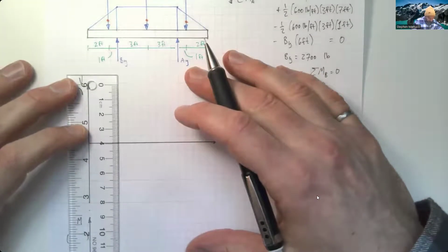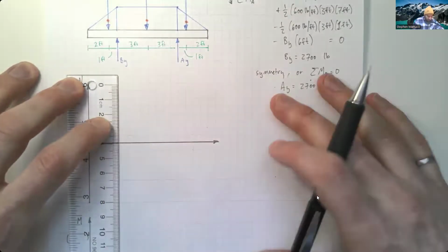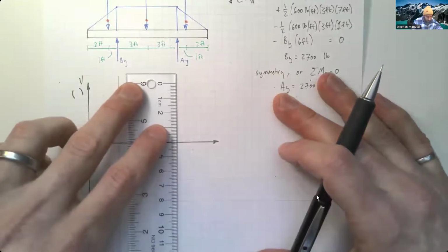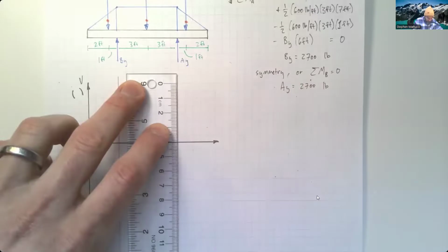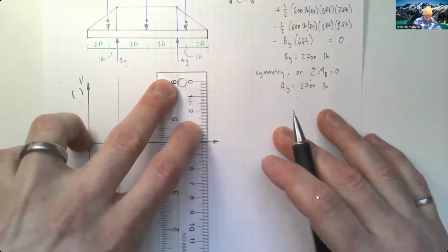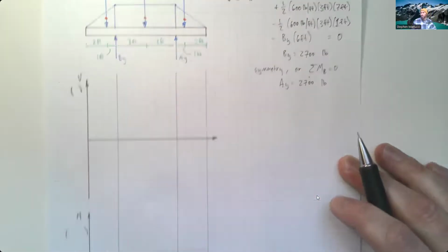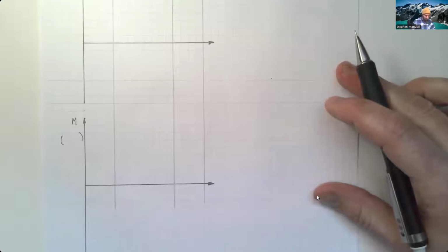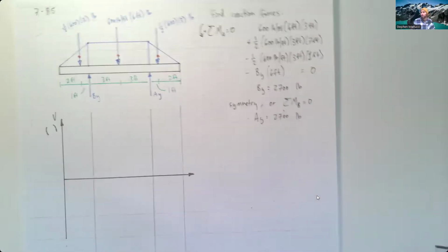So at this point, these are going to be our reactions. Carry one here down at B, carry one here down at A, and I'll carry it down at the end of the beam as well. So these lines make their way all the way down. I ran out of space with my ruler, but we'll adjust those if we need to when we get down to our moment diagram.